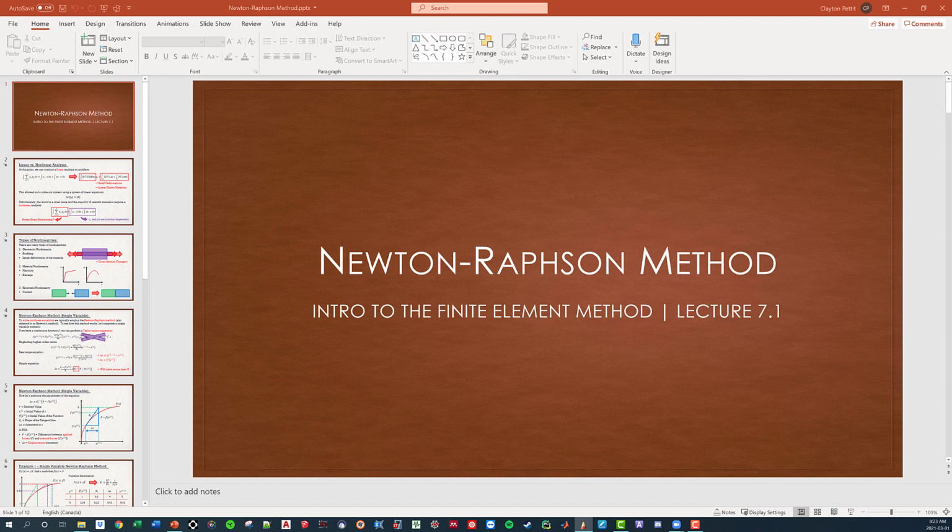But then we also have a third component, which we don't really talk about enough, and I call it Fa, which is our applied force. This force right here is something that we apply directly to the nodes, so that would go in that part over there. If we were to take a step back and look at that, that basically accounts for all the loads we typically see in structural engineering.